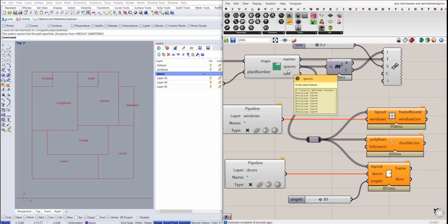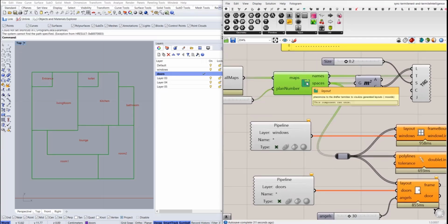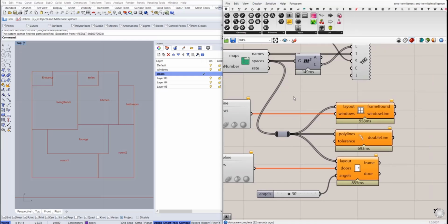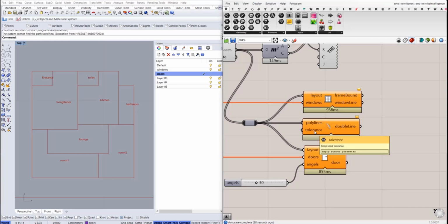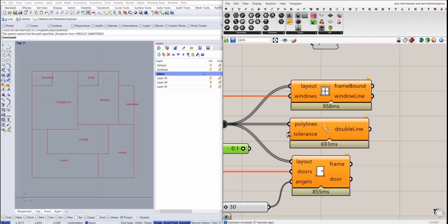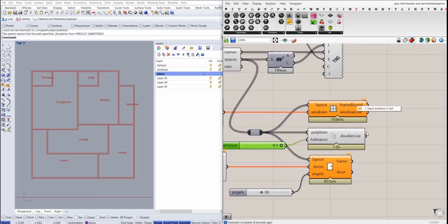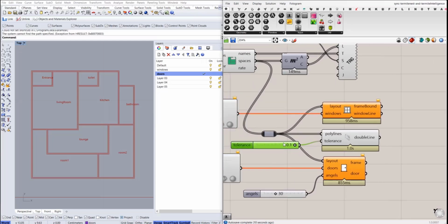So when we call the polygons of the layout from the Termite Intelligence via Termite Nest, there is a conversion of the types to be visualized in the Rhino. So there might be some errors in reading the data for the duplicate points, and this tolerance helps us to clean it up. So I usually go for the value of 0.1, and it's based on the tolerance of your Rhino scene, but just 0.1 is a default value I usually use.